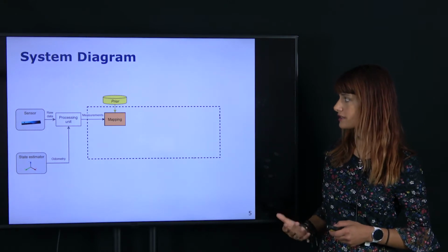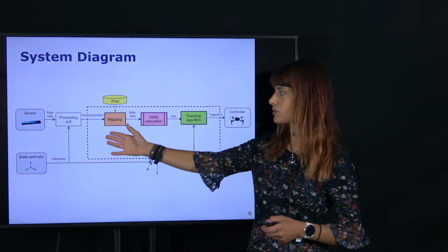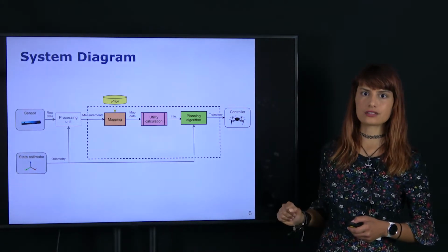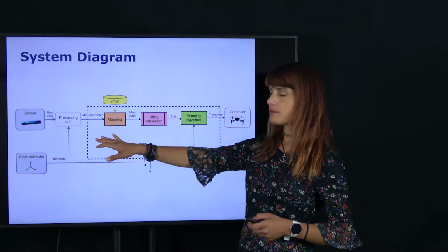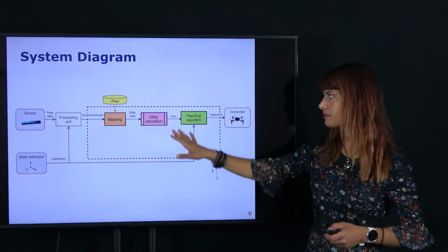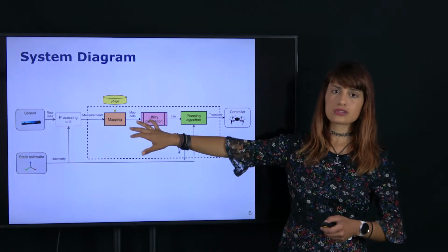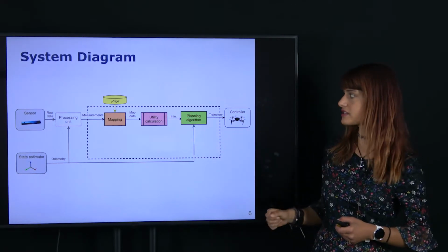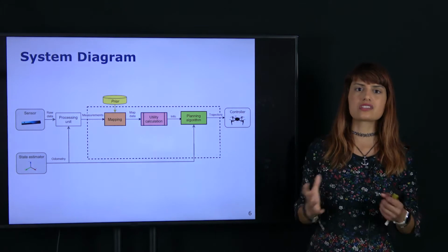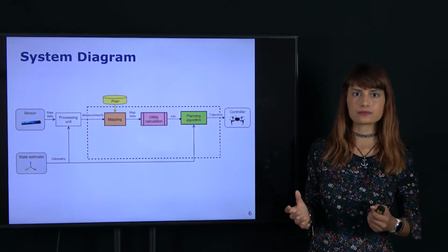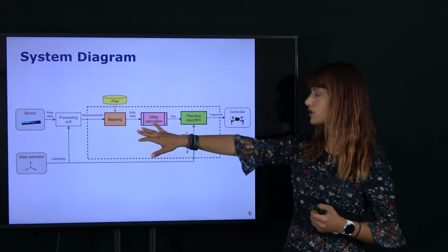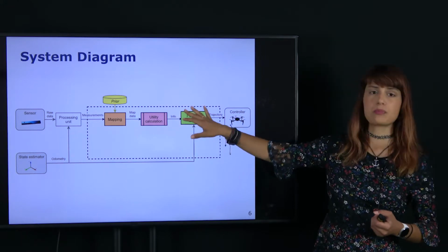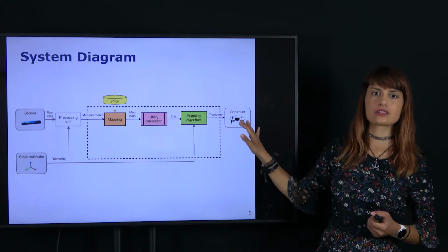And then the key component in robotic information gathering is that we now start to use this map in order to generate informative plans for data collection. So we use the current state of the map, and we have some transformation operation here that uses the map data to calculate information gain of particular points. So this is right now just on an abstraction level how these modules are interconnected. And so we have the map, and we look at the data that we have in the map, and from this we can extract information that we pass to our planning algorithm to generate trajectories for the robot to follow.